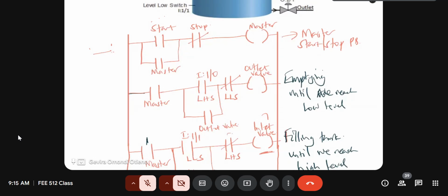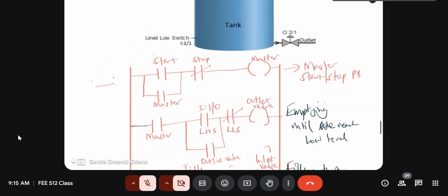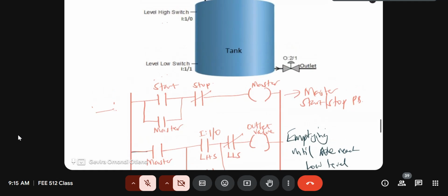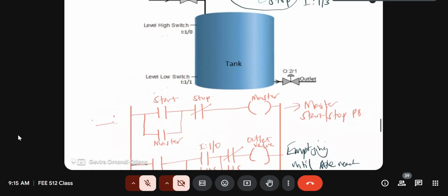Yeah, because if you just have the physical sensors, that's where we'll have those particular situations. You probably have to latch the input, the input devices or the input instruction, and that is why I'm saying we'd just use a physical sensor. Let's say the ultrasonic sensors will just tell us whether water is at high level or low level, and we'll just send the signal to the high level switch and the low level switch, depending on the level of the water. Yeah.